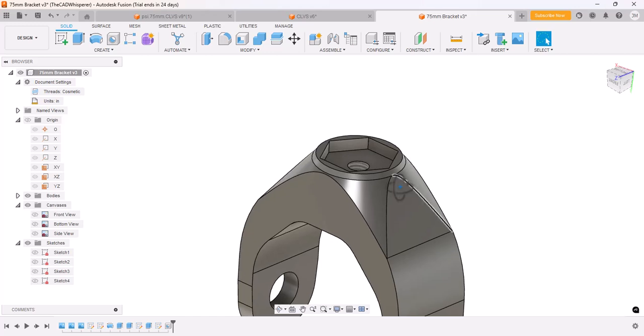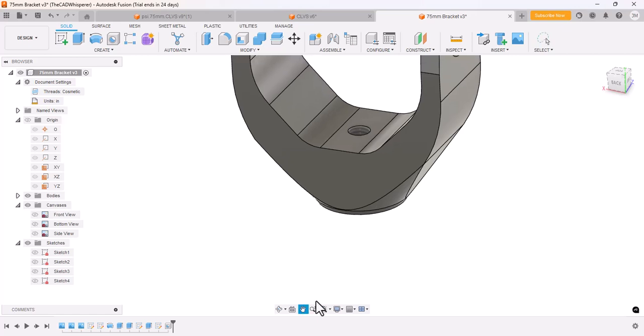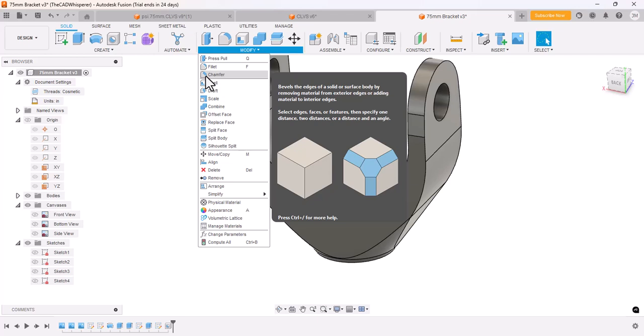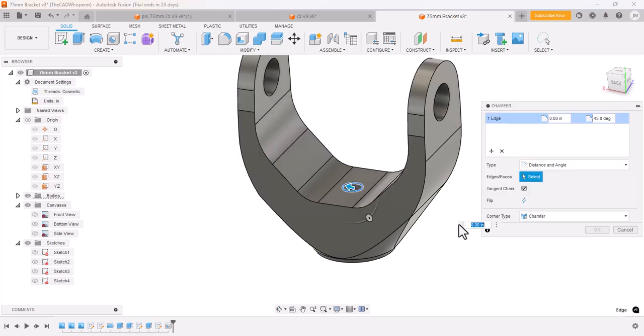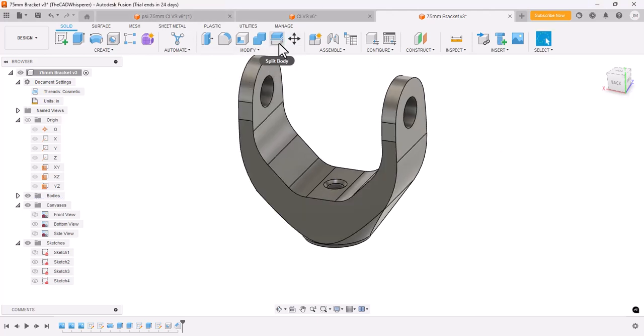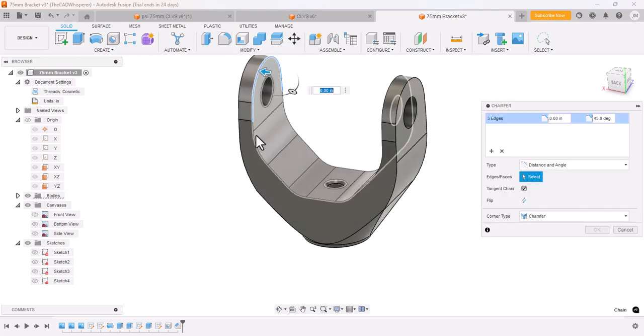and then I'll put the chamfer on here. Now I like to put a chamfer on this end too, just to break the sharp edges. So I'll go ahead and do a chamfer on this end, let's say 0.0625, and I'm going to put some chamfers along those edges. So I'll do a chamfer along this edge. Now the model shows a slightly different chamfer in here. That would have to be modeled if you wanted that difference.